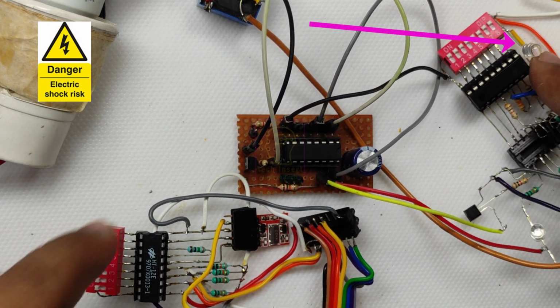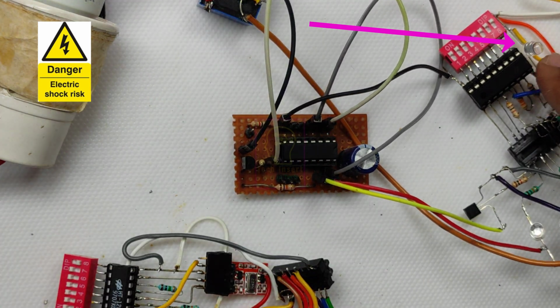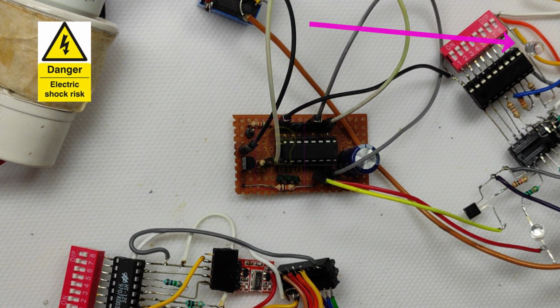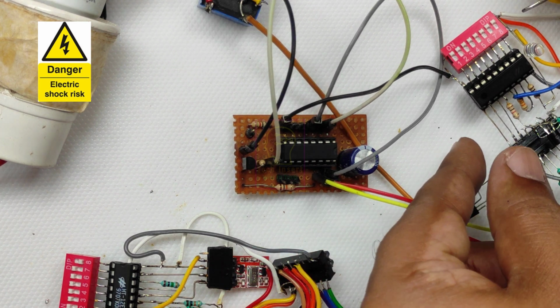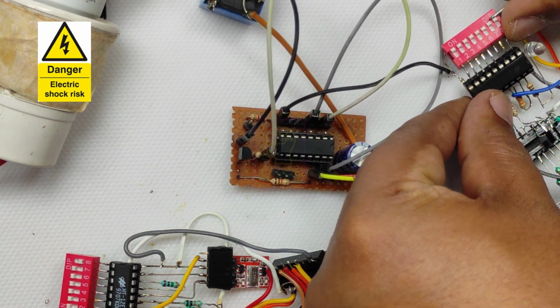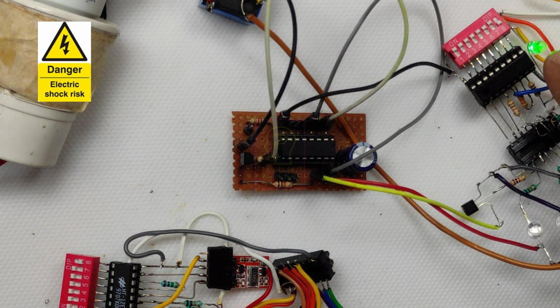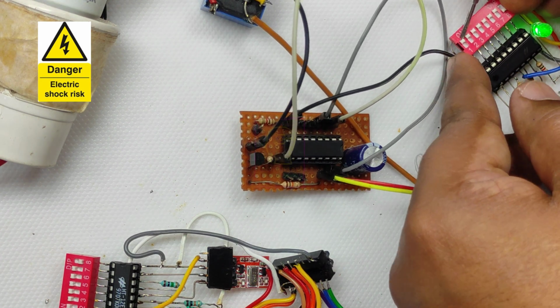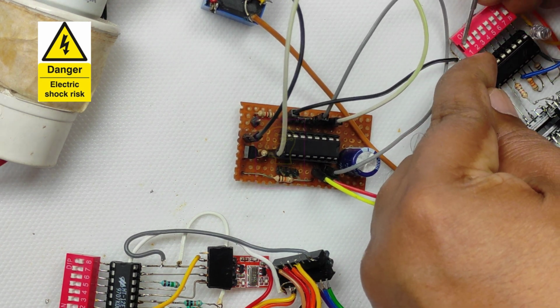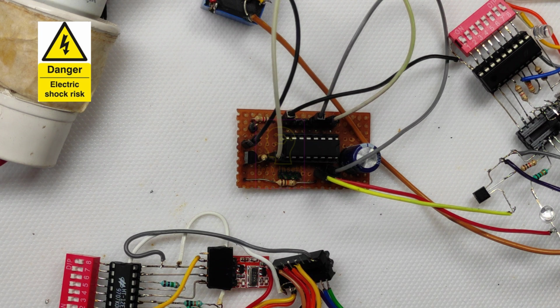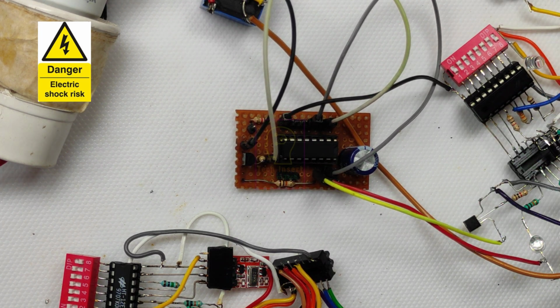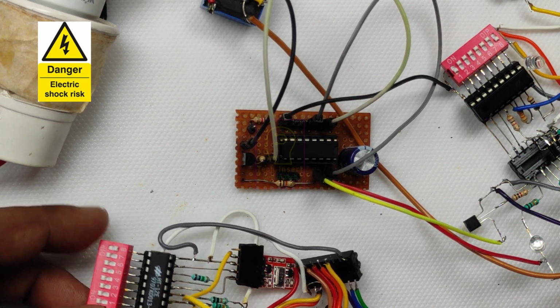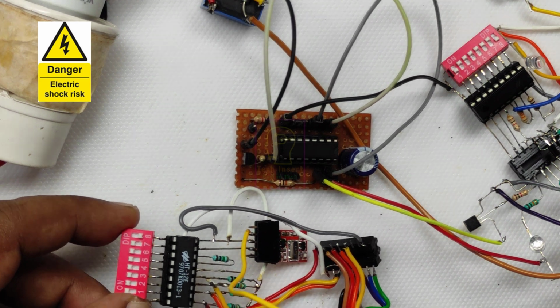Please watch the LED. It is now in off position because the address code which is transmitting is different. The moment I move the 8th pin of the receiver to the off position, the binding resumes and the LED is lighting again. I hope now you understood with the help of address bit how the transmitter and the receiver are uniquely identifying each other.